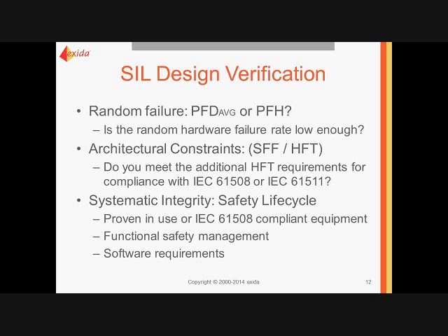Functional safety management, this is what I was saying about how well have you defined and documented and followed your process for developing and producing the piece of equipment. And this also includes software requirements. How well have you defined your software process? How well has your verification and validation been? So all of these things are taken into consideration. And so when you do SIL design verification, you don't just look at the PFD average or the PFH. You have to look at all three together, and they will have an impact on the overall SIL.